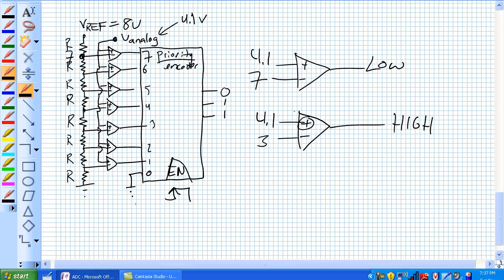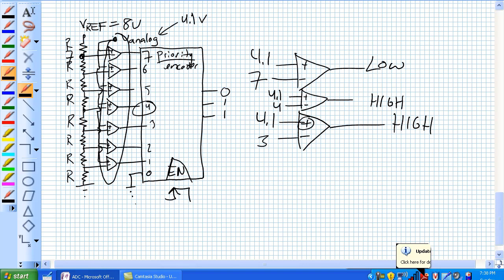So yeah, 3 is still going high, but in between here, this guy is giving a high value. Okay, long story short is basically a flash, i.e. simultaneous analog to digital conversion. Everybody's looking at it simultaneously, and according to what we just discussed, if everybody's looking at it, i.e. the number of bits you've got there, look at all that hardware that comes with it.